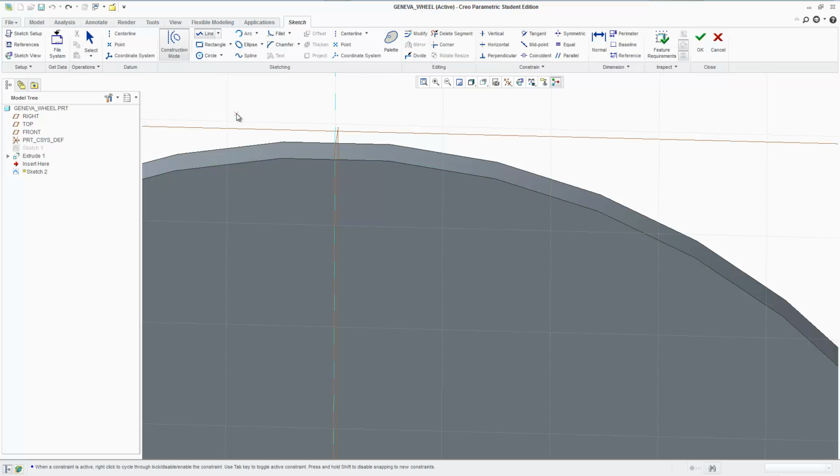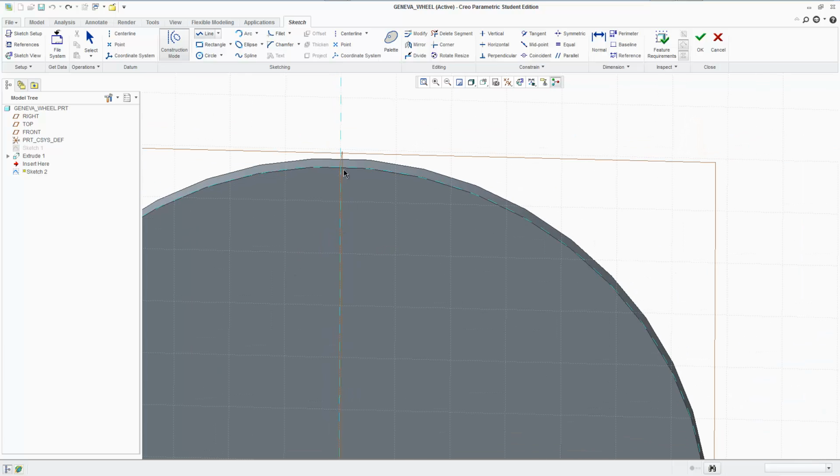So if I make a circle, alright, the order matters too. You're going to have to select the tool that you want to use first, have that activated, and then select the reference by holding that Alt and clicking. I'm going to make a construction line. I'm going to hold down Alt and click. The center plane is already my reference, so I'm going to start here. I'm going to click and drag, and we have a dimension here. My size that I came up with was 2.34315. Okay, so that's my construction line, and I'm going to make a circle at that point now.